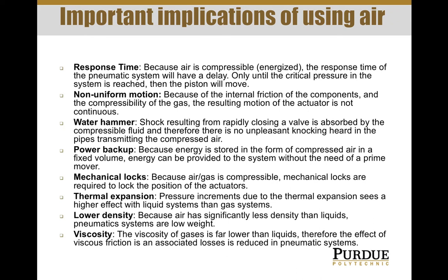All right, some important implications of using air. Here's what you have to take into account when you are using a pneumatic system. The response time. Because the air is compressible and it's taking energy from the system, the response time of the pneumatic system will have a delay. Only until you reach a certain critical pressure to break things from moving, only then the piston will start moving. So it will have a delay that you will not see so much in a liquid system.